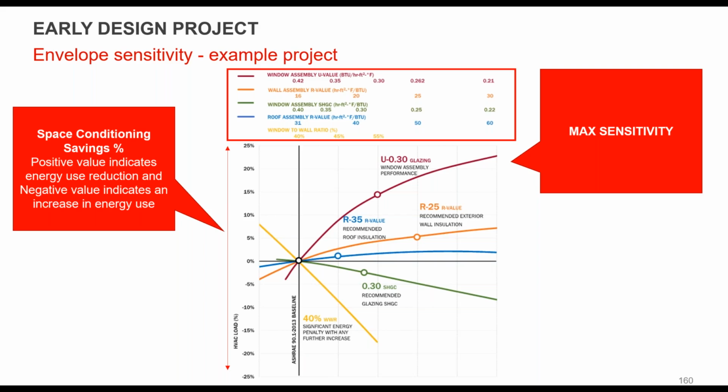How big a variation do we see when we simplify geometry? 1% to 2%. It's not a lot at this point. There are many other things, as you see: the inputs around glazing percentage and U-values are going to have a much greater impact than that geometry, except for shading, and I think that's really key. So even a large-scale building is still going to be not insignificant, but not the driving factor at that point. How would you decide to simplify the building in slide 157?